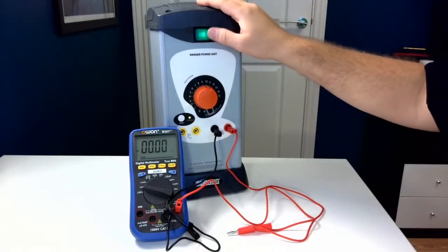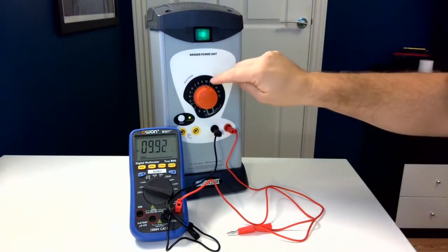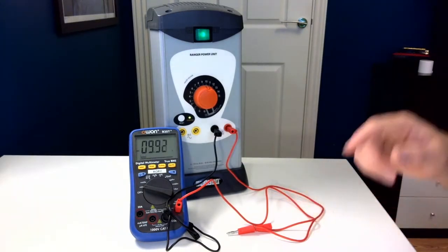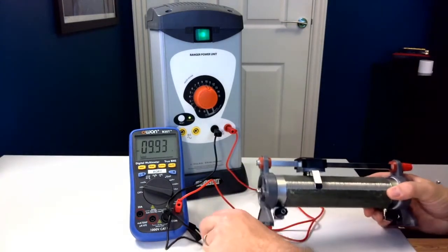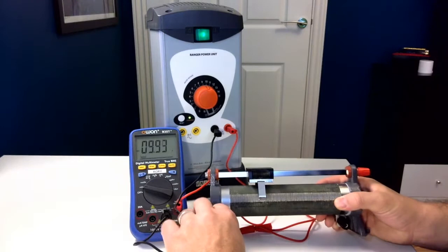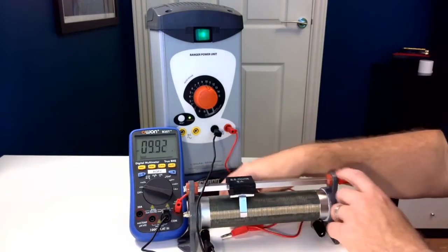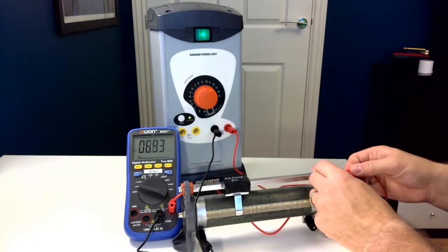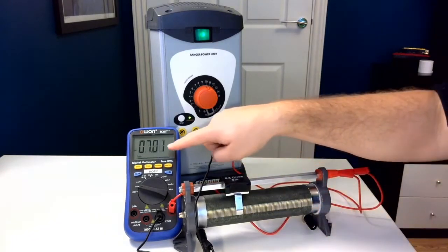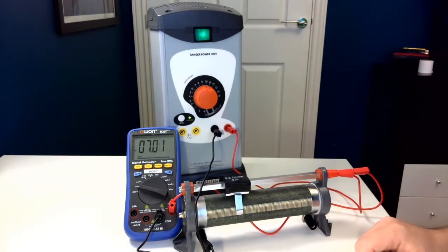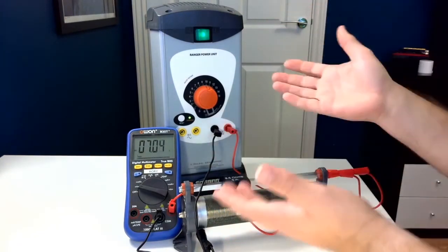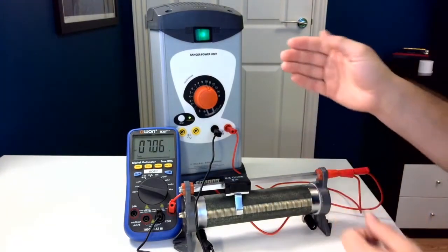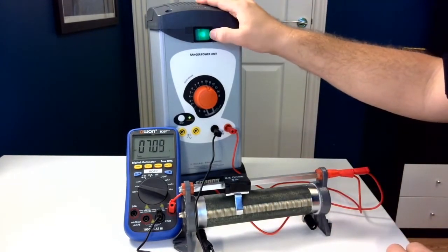Students will often flick on their power supply and expect 10 volts on their power supply and 10 volts on their voltmeter. They will then be disappointed when they plug in a component like a bulb, or in this case a resistor, that the value they get out is lower than they're expecting. So here it's gone down to 7 volts. And they will think that this is a mistake with their equipment. Maybe they've not got a very good power supply. It's not a mistake. It is just the fact that the power supply has got an internal resistance.